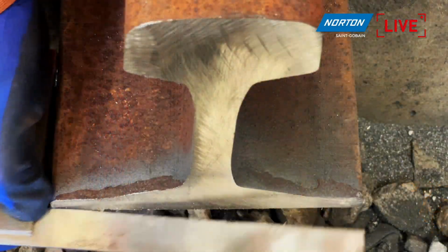Right. So if each part of the rail, the part you cut and the part you're trying to join on, are not exactly parallel to each other, that's going to cause an issue when you're going to weld. Absolutely. It's very simple. Now, I think we've got a little video about this, how this is measured on trackside, and we'll have a look now at how the cut should look and how it's checked out there on track for this attribute. Martin, if you can run VT, yeah.